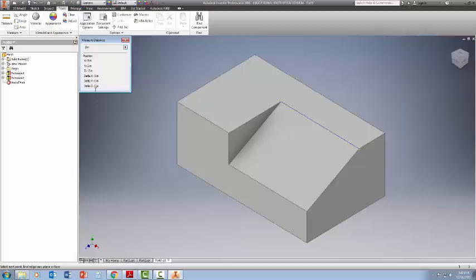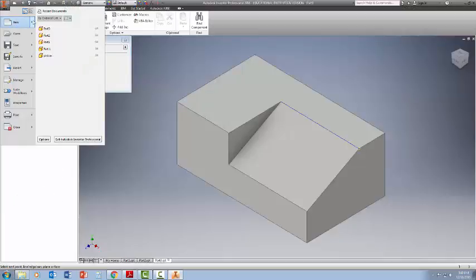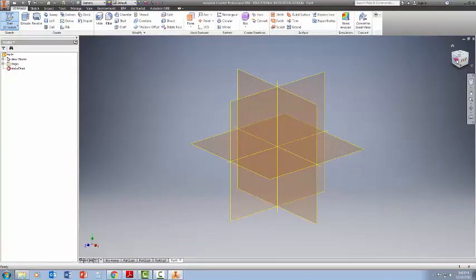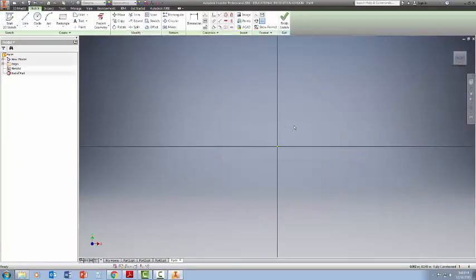Let's click on Inventor, File, I click a little arrow, go to Part, Start New Sketch, I click on Front, click on the front plane, Rectangle, click there, I'm going to just bring it over. The top is highlighted, so let's do that one first.